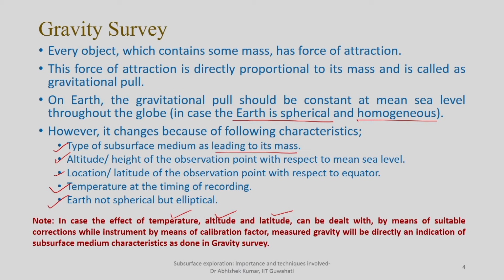If you apply this correction, you will be able to understand how much is the corrected gravity value at the site of interest. Of course, you have to apply some kind of calibration factor also, depending upon what kind of instrument you are using. So, that is going to give you the measured value of gravity at the site of interest, which is an indication of subsurface medium characteristics.